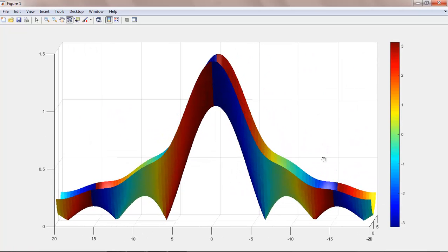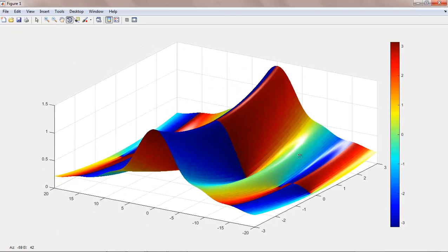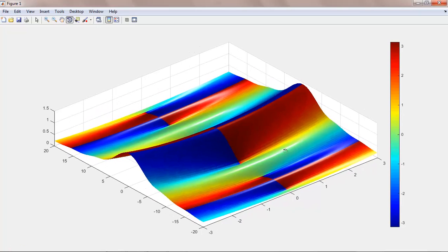If you get anything out of this plot, because for signal analysis, you don't usually use the Laplace transform. You use the Fourier transform. So you're not often going to actually be looking at plots like this. But what I want this to illustrate to you is that the Fourier transform lives on the imaginary axis. That's an important point to remember. Maybe this example will help that concept be more solidified.